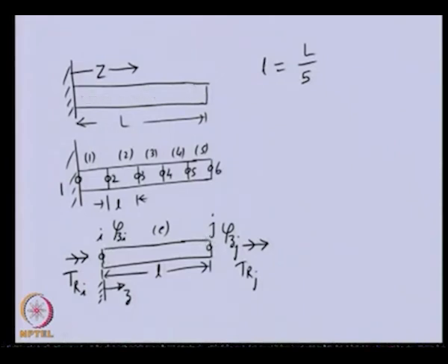So, obviously, that governing equation will be valid for this element also, but in this particular case, as I mentioned, we will be seeking the solution at the nodes only, and if we want the solution in between, meaning the angular displacements in between, then we will be using some kind of shape function. In the finite element method, this shape function is generally a polynomial.